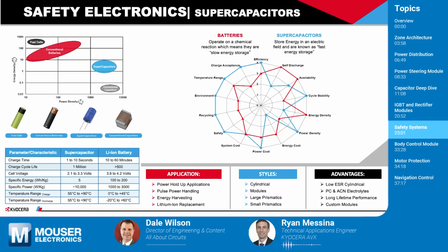But this is a big deal because many zonal architecture systems do not have constant power draw. They have discontinuous loads. They also might have a need for hold up if power gets disconnected. Say with a lot of vehicles, especially with EVs, if the battery's dead, you can't open the door. So if you need to get out and you can't, that's a problem.